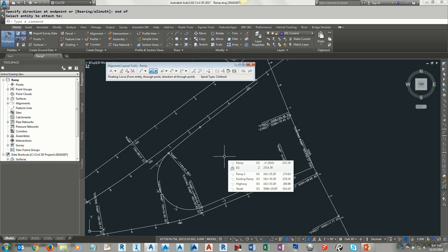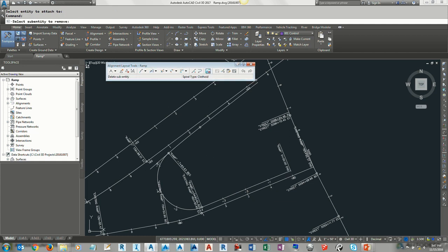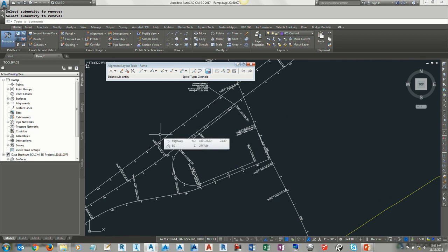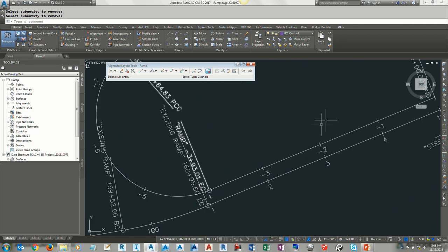Yes, you're right. I've got an ambiguous direction, left or right, so I need to get rid of that temporary segment that I made. So I'll pick this guy, get rid of it, and now I get the geometry taken care of. So that completes my alignment. It doesn't end here though. I got the alignment geometry good, but the whole stationing is messed up.